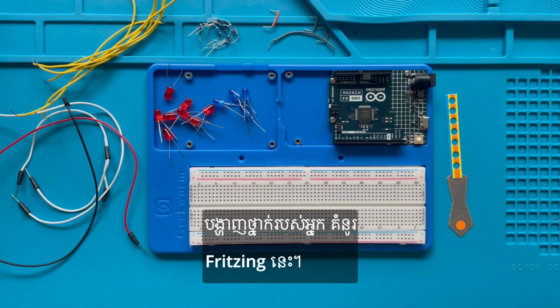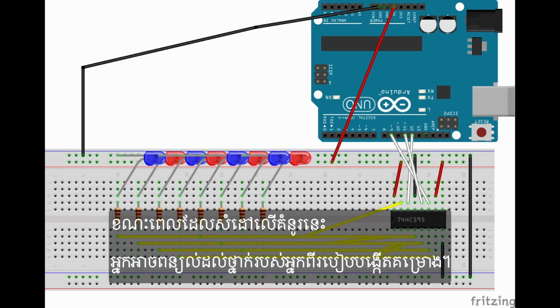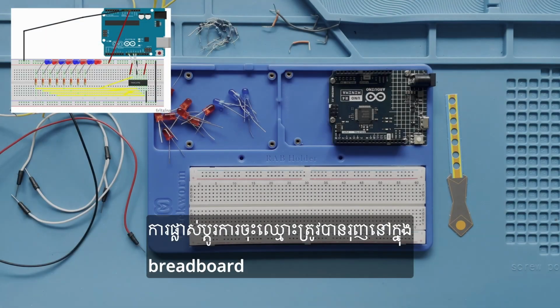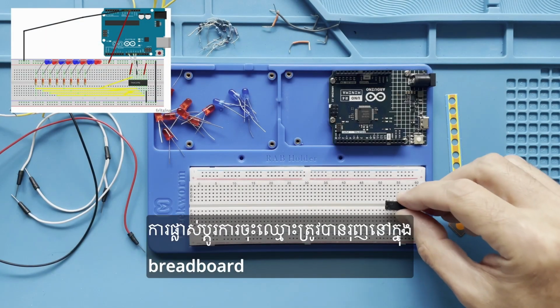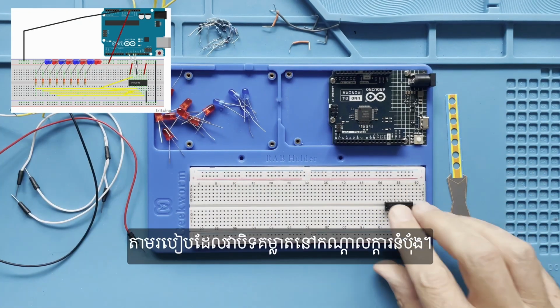Show your class this Fritzing drawing. While referring to this drawing, you can explain to your class how to build the project. The shift register is pushed in the breadboard in such a way that it bridges the gap in the middle of the breadboard.